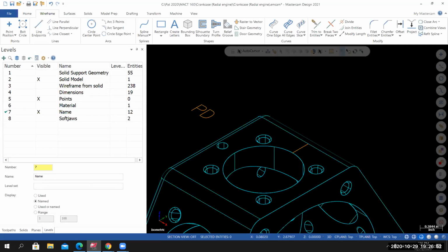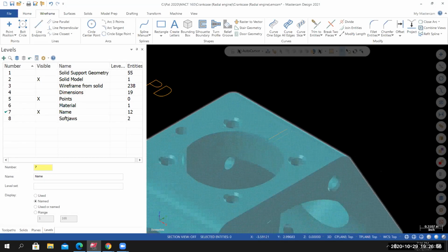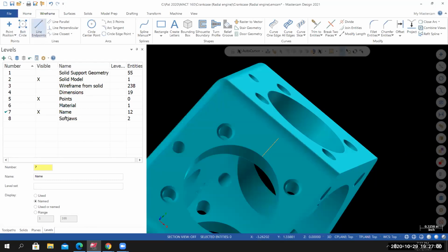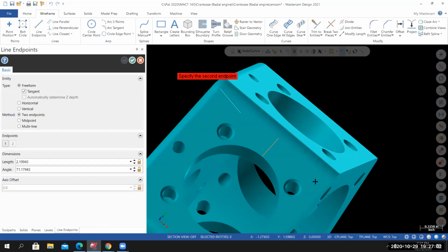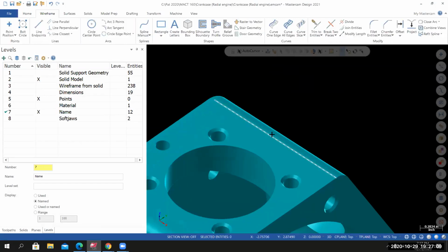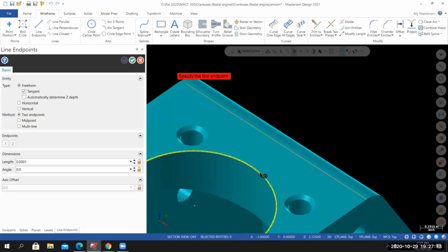And then I'll go back to this view. It's close enough. If you wanted to get really precise, you could lock onto that endpoint, and now that it's considered real geometry, if I go to line, I can go to the quadrant.